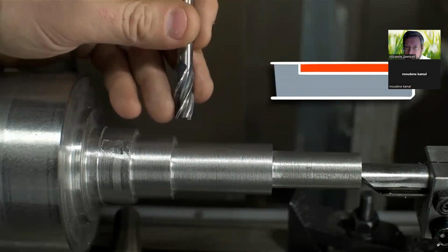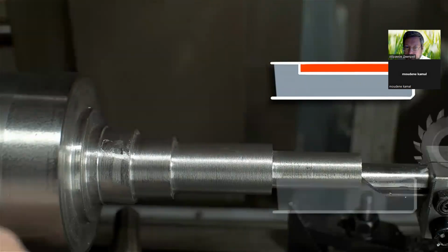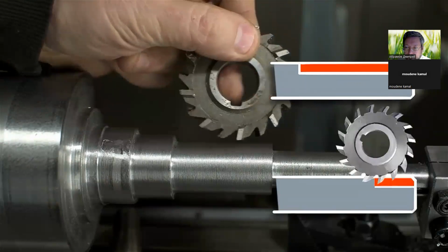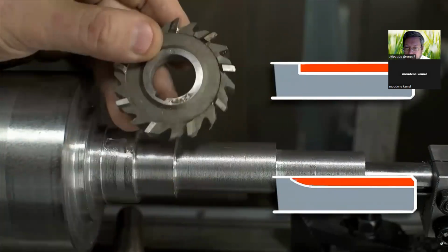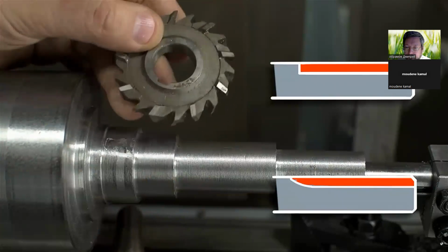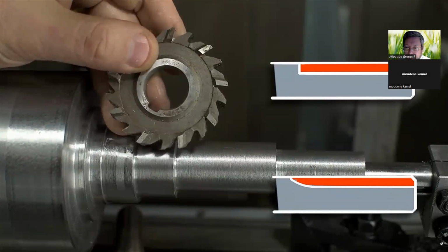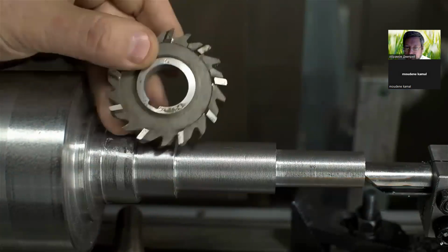I couldn't find anything specifically in the book. I didn't dig too hard, but PTO shafts usually have that cut feature taper out. So if I come in here with a milling cutter and do the same groove, that cut will feather out. It won't stop abruptly. I don't know if that's necessary, if it's done to reduce stress concentrations, or if it's just a result of the manufacturing process. In either case, I'd like to mimic that lead out on the spline cut. So I'm going to use one of these.